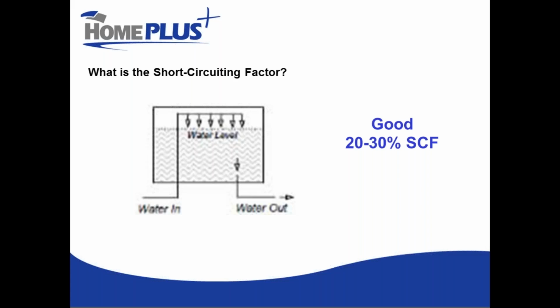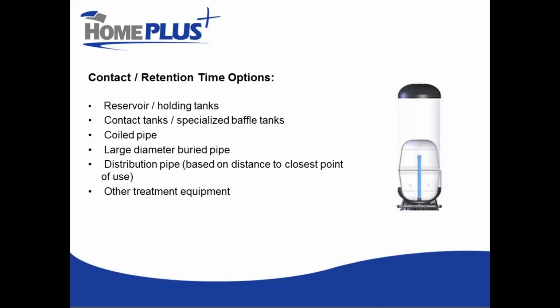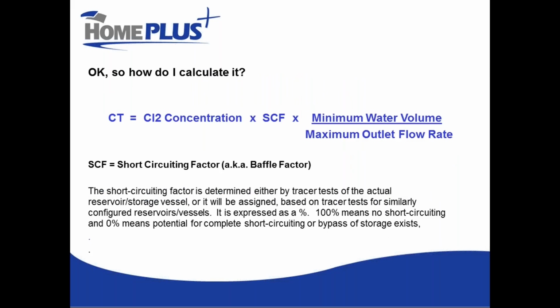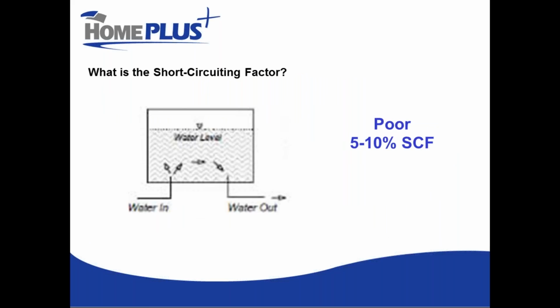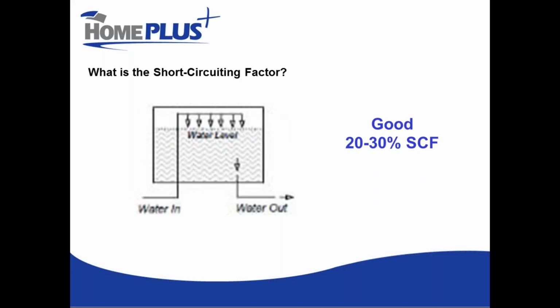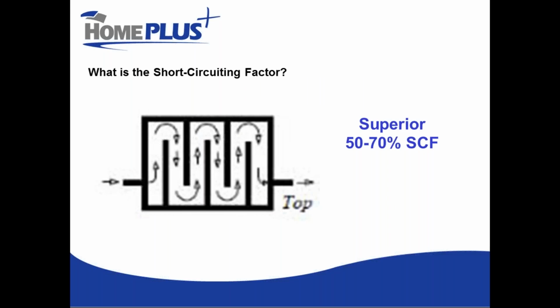In some cases, you can buy baffle tanks where studies have already been done and they will provide the baffle factor for you. So for instance, this particular tank right here has a baffle factor of 0.6, which is actually really high, 60%. And that's been tested by the manufacturer, third-party endorsed and accepted by the health authorities. But when you're talking about reservoirs, it can be a little more subjective.